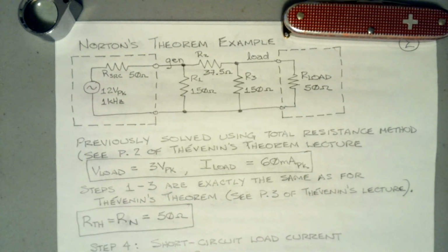When we model the output of transistor circuits, we wind up with, say, a dependent current source and a shunt or parallel resistance in a sort of Norton equivalent. And in power supplies, a voltage source and series resistance. These are just really good tools to have in your toolbox and to know how to use.